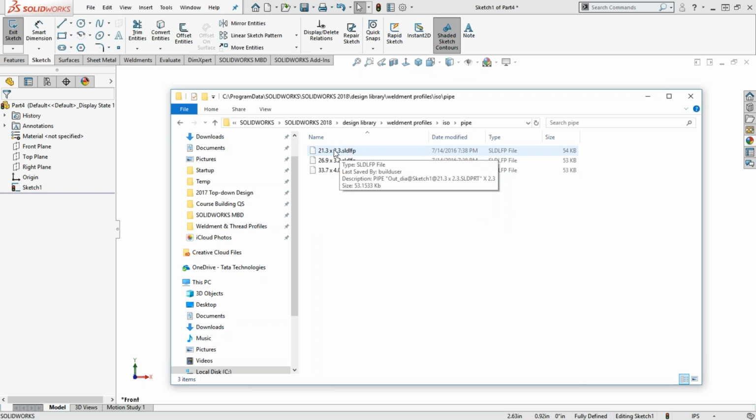Now in this case, they have three different SOLIDWORKS library feature parts, and so rather than being SLDPRT, these are going to be SLDLFP parts, so for library feature. In this case, there are three separate ones. I like to keep things a little bit leaner by using configurations.